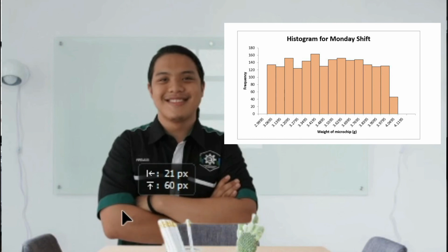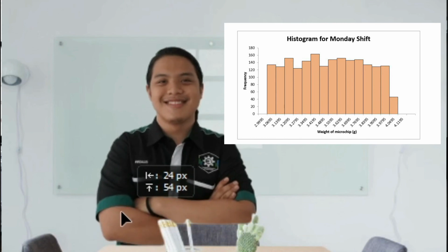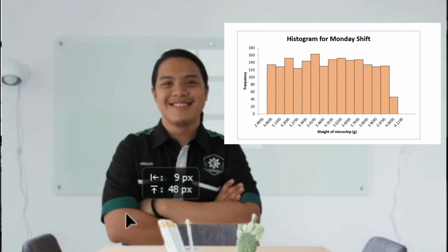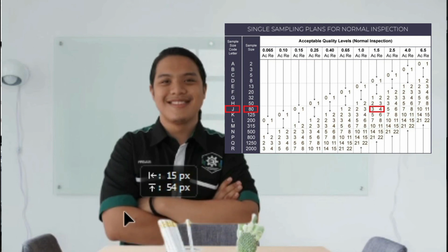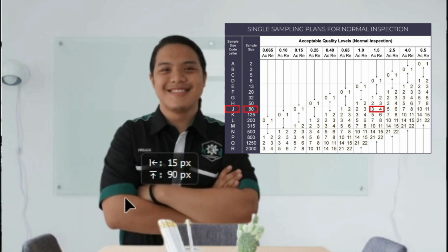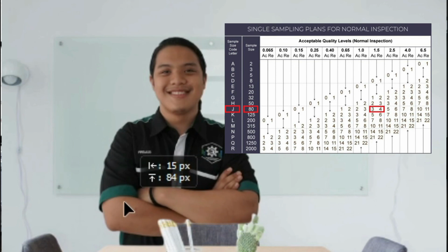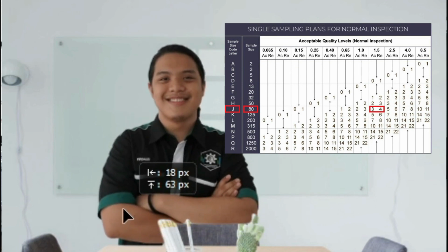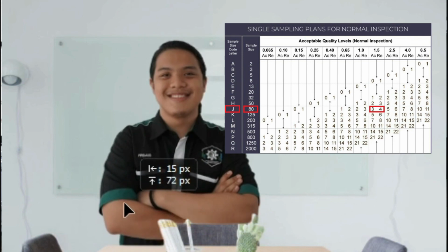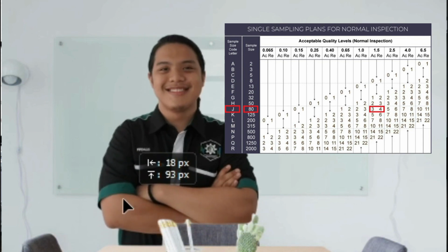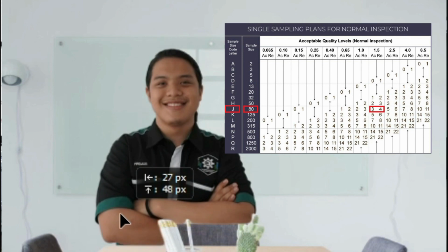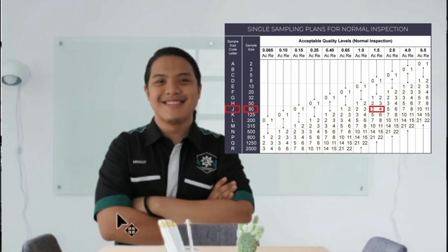This can be fixed or improved by creating a response plan on the manufacturing, such as AQL, or acceptable quality limit. Acceptable quality limit is an important standard used in the quality control industry. It's defined in ISO 2859-1 as the quality level that is the worst tolerable over the course of many inspections.